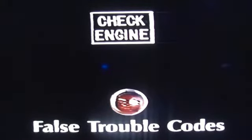Repeating the code check step may be the most important time you spend in your diagnosis, because it can reveal what is called false trouble codes. Here's an example of what can happen. Let's say that after returning from your road test, you turn on the ignition, see a 12 code which indicates diagnostic capability, and it is immediately followed by another 12 code sequence.